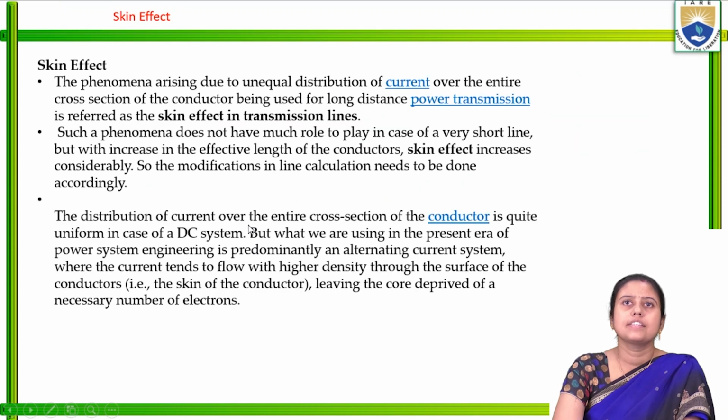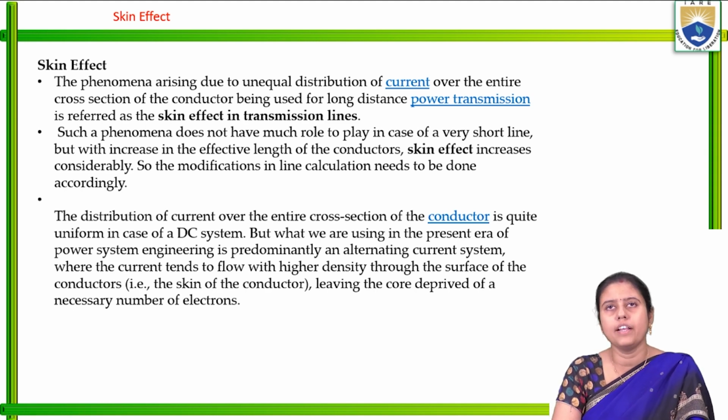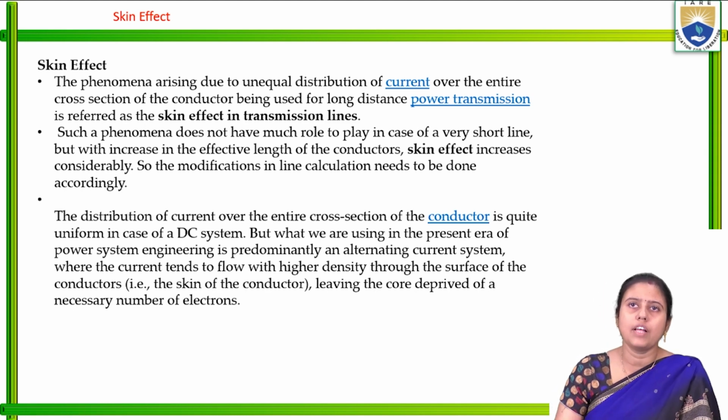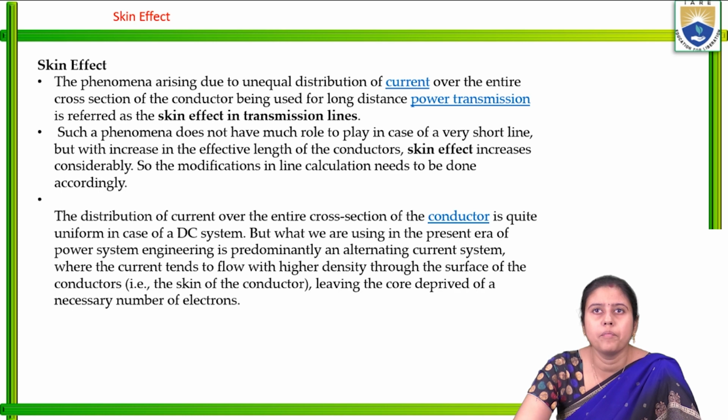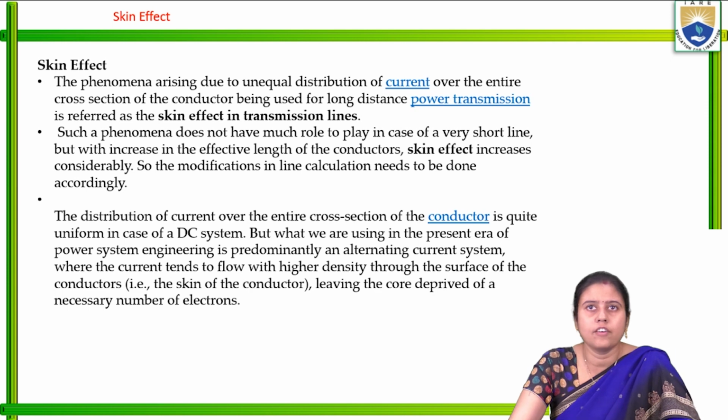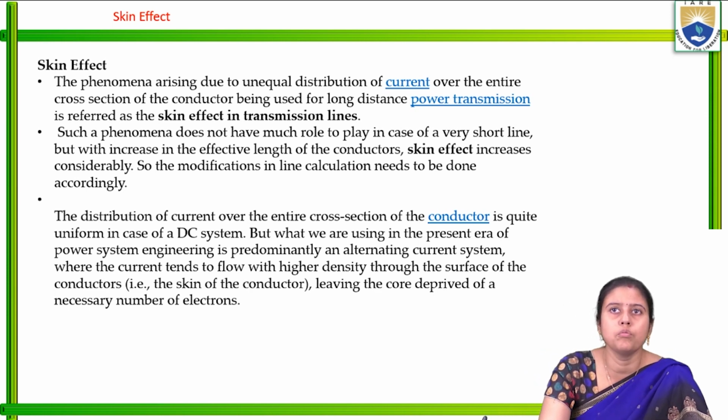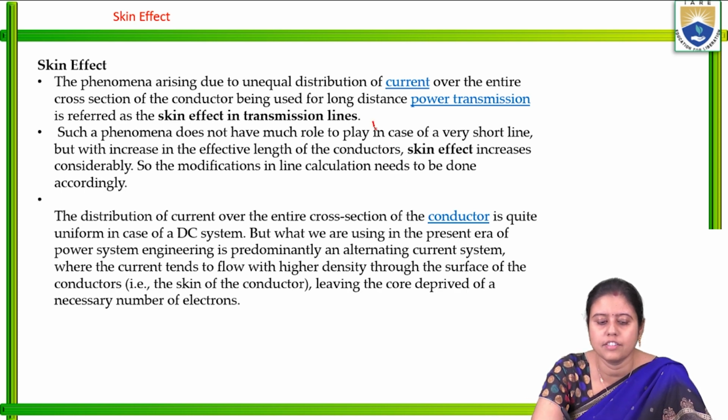What is skin effect? Skin effect is a phenomenon of electric lines arising due to the unequal distribution of the current over the entire cross section of the conductor being used for long distance power transmission. It is referred to as the skin effect in the transmission line. Such a phenomenon does not play much of a role in the case of short lines. It is only effective for long lines.